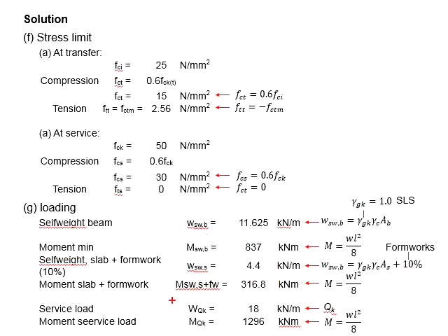Then we will have to calculate the service load. It is QK that given in the questions, 18 kN per meter. The moment caused by the service loads is given by the equation here, which is 1296 kN meter.